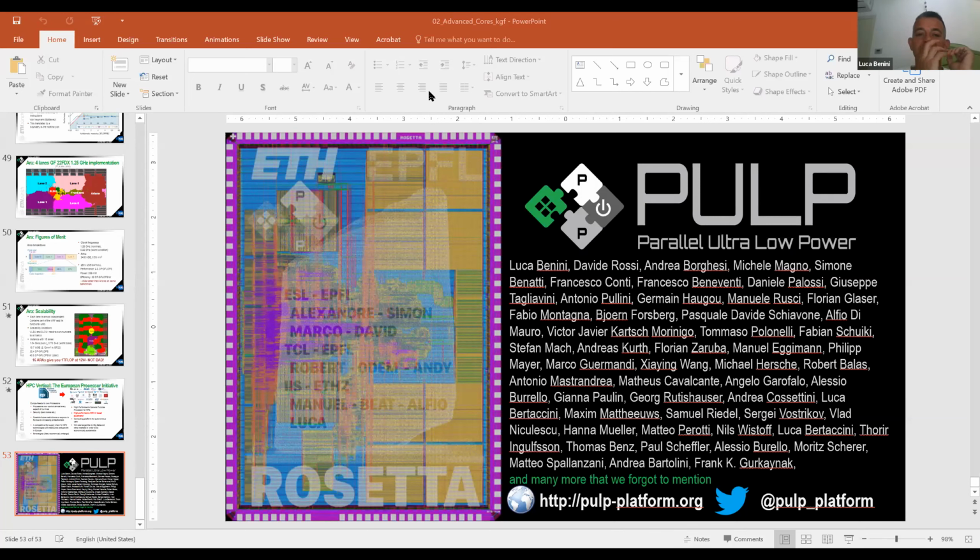So what is the target of a formal verification? Primarily, the target of a formal verification is matching the implementation, RTL implementation typically, with a golden model that has been specified in a formal language. The golden model is specified in a formal language, which is fundamentally a logic language that specifies the implementation and the functionality, and then you automatically, using various techniques that I'm not going to cover today, verify the matching between the golden model and the implementation.